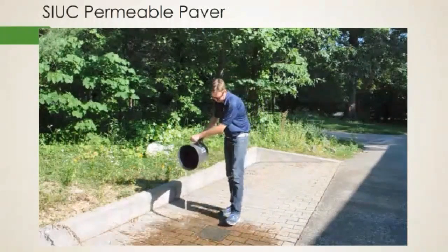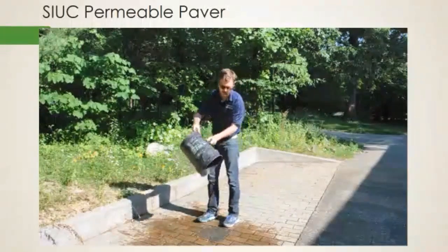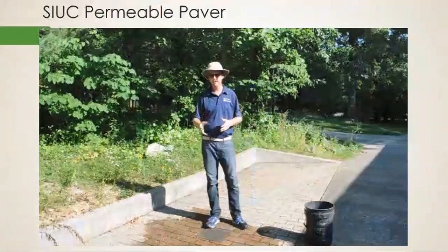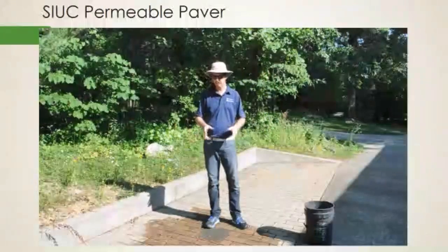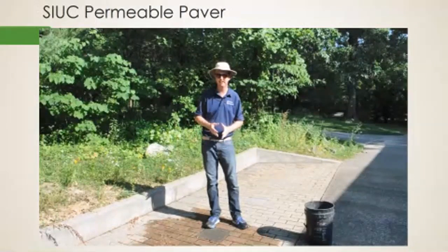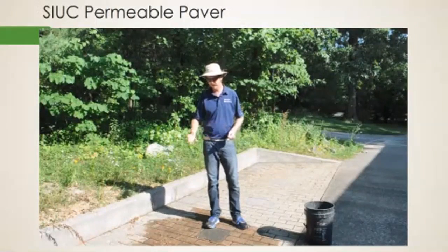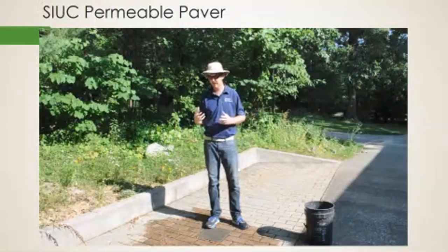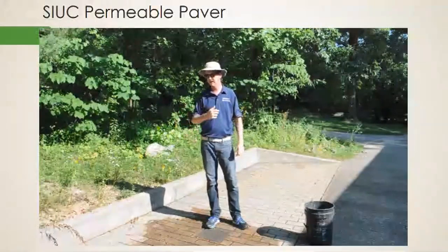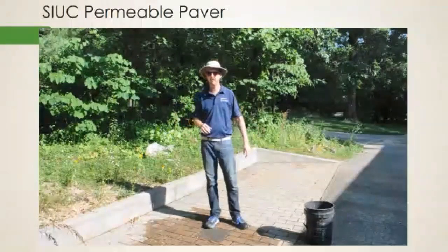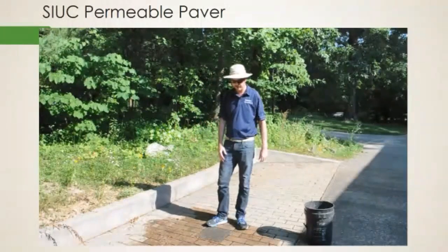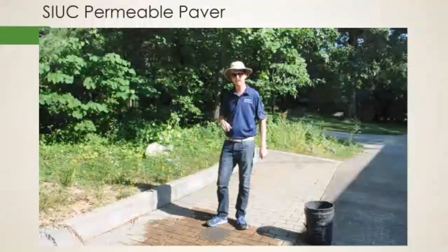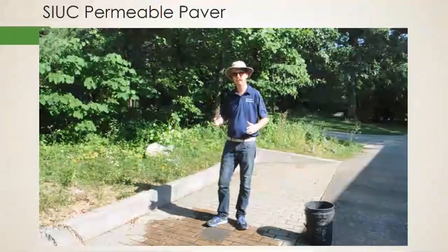blocks. And over time, these do get clogged with organic material, debris. They can build up things like silt, soil. Sometimes moss can grow in between there, and so they need to be power washed out occasionally or vacuumed out. Somehow we need to periodically clean the debris out so that this functions at its optimal level and works as it should to keep moving stormwater away from our walkways and our impervious surfaces. So that's really the basics of how this one works, and we'll take a quick look at the aggregate tile on the green roof, and that's another pervious pavement system.